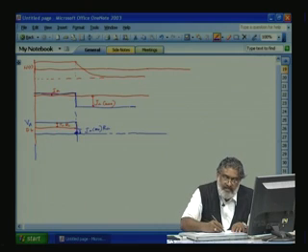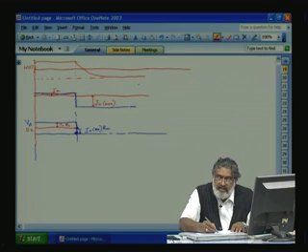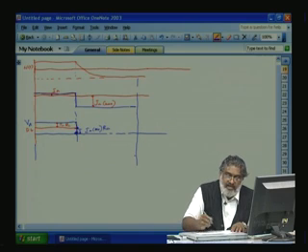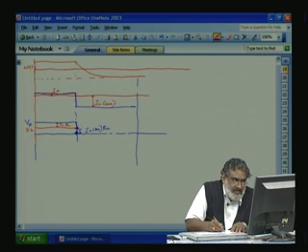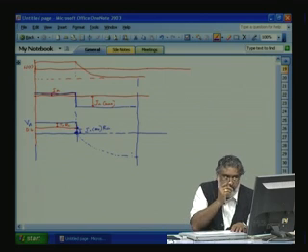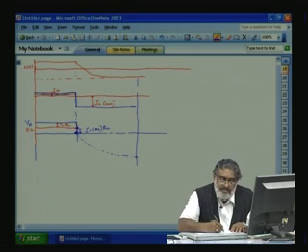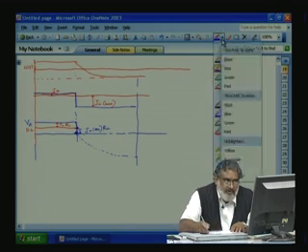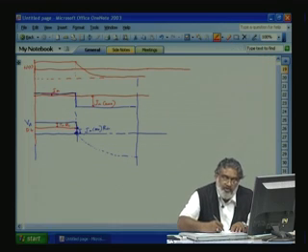Now, here onwards, back EMF cannot change instantaneously, speed cannot change instantaneously. Here onwards, till this speed is reached, we are varying the armature voltage. So, that armature voltage from here onwards slowly comes here. As the speed decreases, you always maintain the IA maximum. So, back EMF will also slowly decrease with respect to speed. So, back EMF will vary like this,